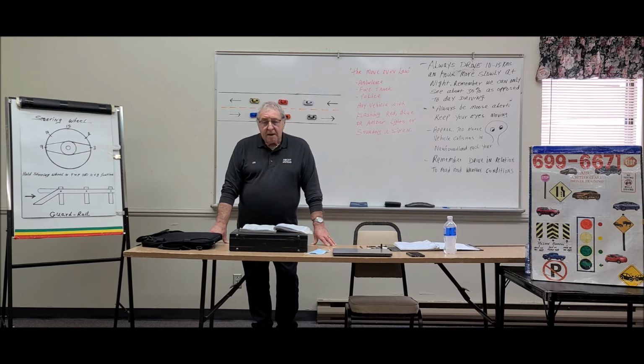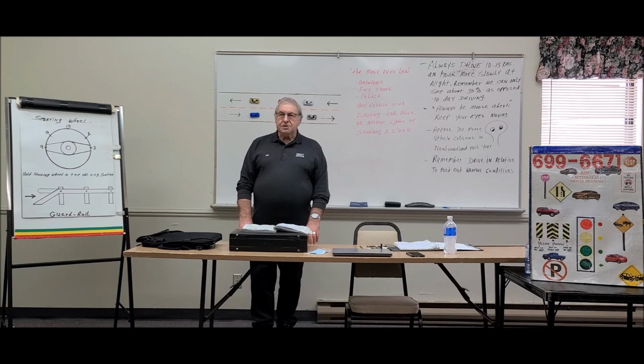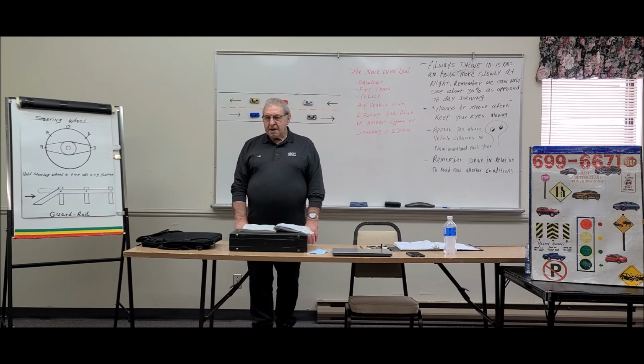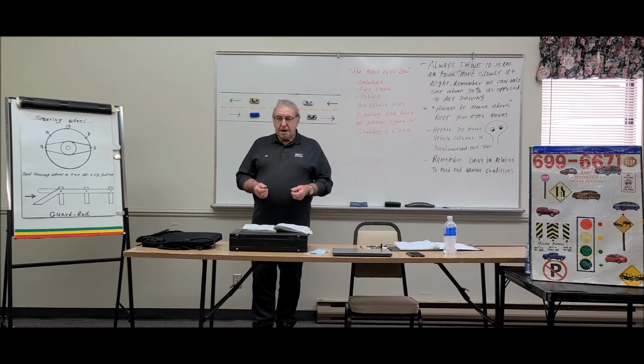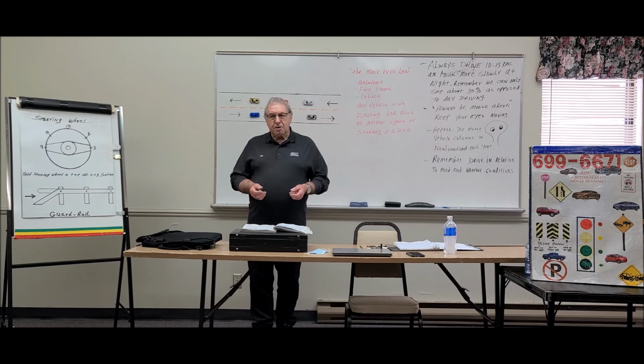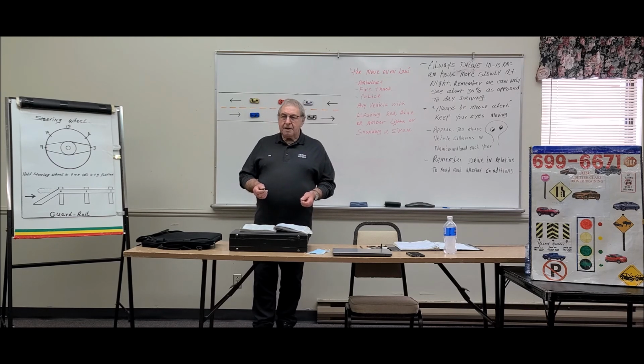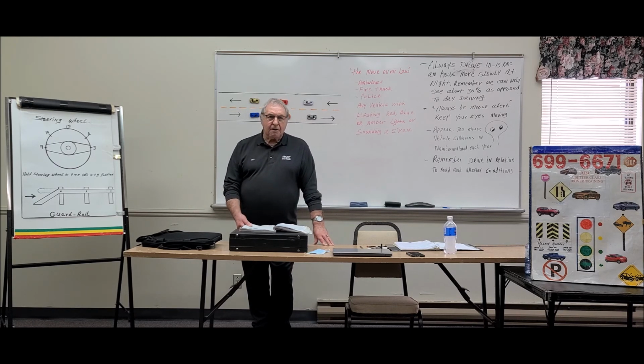But like I'm saying, not all cars have that feature. Any car with air conditioning, if you're using it, is probably going to be a little bit harder on gas than a car that doesn't have air conditioning, because there's a compressor there and the engine is hooked with a belt to it, and of course the engine has to keep that compressor turning, so you're robbing a bit of power from your engine. So it's got to take more gas to compensate for that loss of having to turn the compressor. So a car will be slightly harder on fuel if you're using your air conditioning as opposed to a car that doesn't have air conditioning.